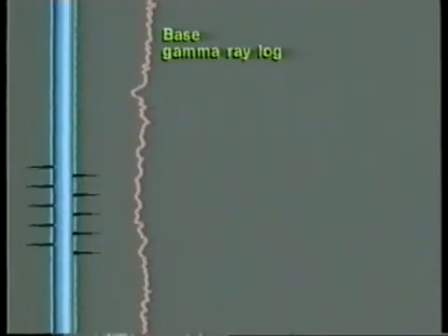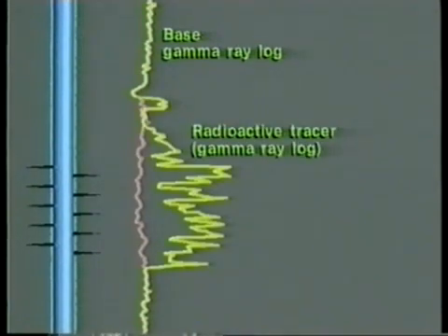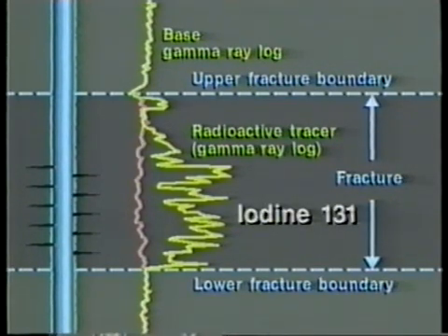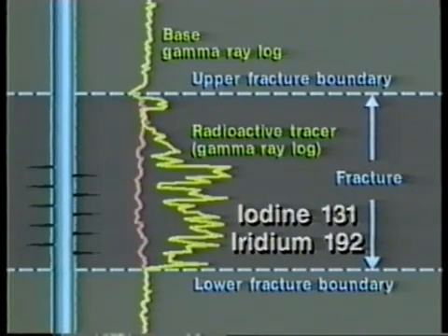The third technique for qualitative determination of fluid movement involves injection of radioactive material and subsequent gamma-ray logging. Radioactive tracer techniques are used primarily to determine fluid movement into injection wells and to locate the placement of injected material, such as fracture proppant. The tracer may be added to the injected fluid at the surface or released downhole. For liquids, the most common radioactive isotope tag is iodine-131, introduced as sodium iodide dissolved in water. Iridium-192 is often used for tagging sand or proppant.